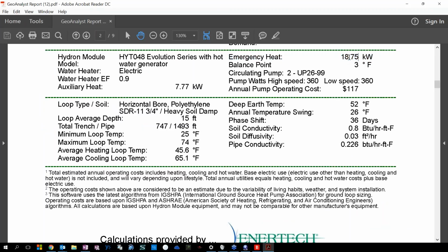So this one fellow would select a 20 kilowatt heater for that job. And he says, I would pick a 20 kilowatt heater for this because if something goes wrong, you always want that emergency heat to keep the house warm. I disagree. I believe that that's like putting a furnace next to the furnace that you just installed in case the first furnace doesn't operate. This is a little bit redundant for me.